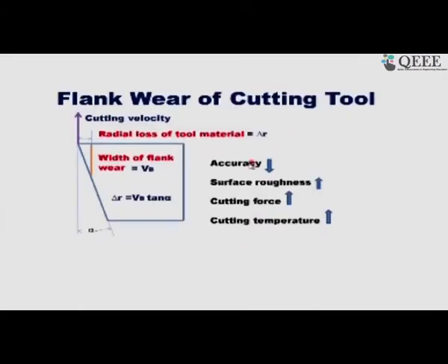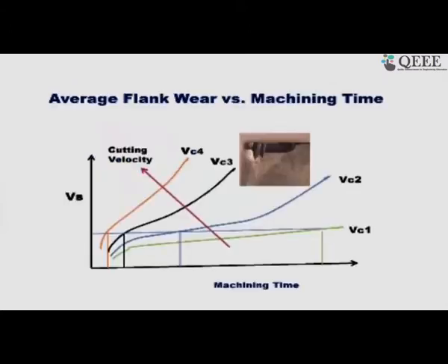So, friend, here it is the summary. We have already mentioned accuracy will be impaired, surface roughness will be affected, it goes up, cutting force goes up, cutting temperature goes up. So, those are the few things one has to look into. So, finally, what we find?